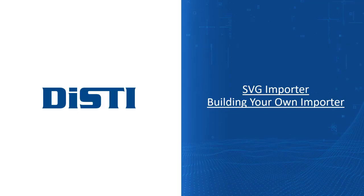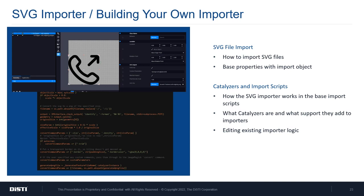Now, last, this is kind of broken up into 2 sections, but first I want to cover the SVG Importer. And as we cover the SVG Importer, I want to go a little bit more in depth into the actual import system that GL Studio utilizes and how you could edit that or add your own importers into GL Studio. First, for SVG files, we do support vector-based SVG textures. Same as the others, you just drag and drop them right in. GL Studio will automatically create an underlying polygon that will have that texture in it, but as you scale that texture in the editor, it will automatically re-rasterize for the new scale that you've given it.